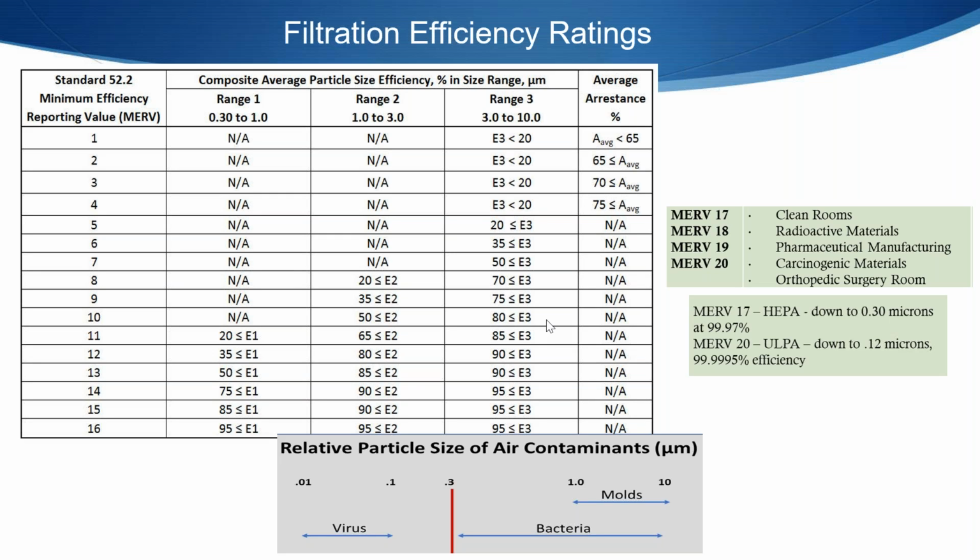So to be very clear, UV manufacturers are not opposed to particulate filtration. In fact, most responsible UV manufacturers recommend a minimum level of a MERV 8 filter prior to their system to make sure that the system does not get bogged down with dirt or debris or damaged by debris. So UV and filtration go hand in hand. You should not have UV without filtration. To make another point of clarity, UV is not a particulate filter at all. So you definitely need to meet the needs of your system with the appropriate level of particulate filtration.